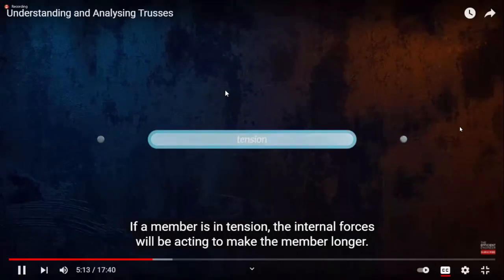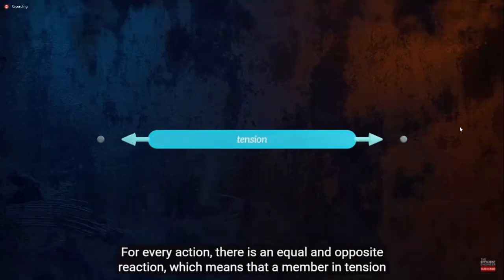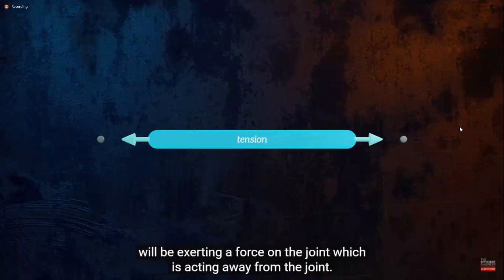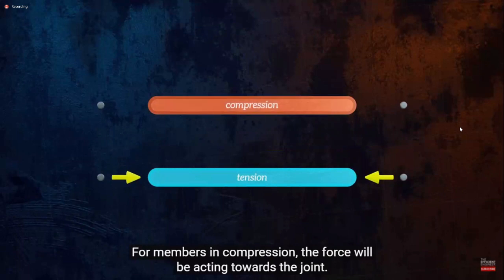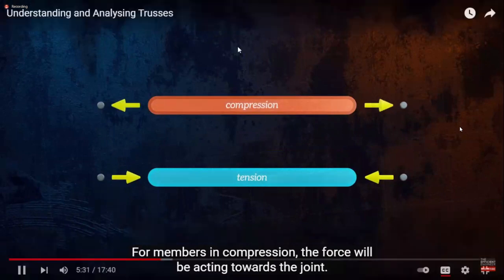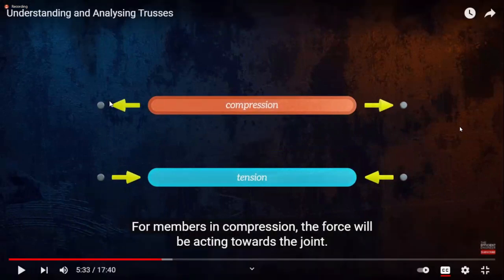If a member is in tension, the internal forces will be acting to make the member longer. For every action, there is an equal and opposite reaction, which means that a member in tension will be exerting a force on the joint which is acting away from the joint. For members in compression, the force will be acting towards the joint. This is a very important point to understand.